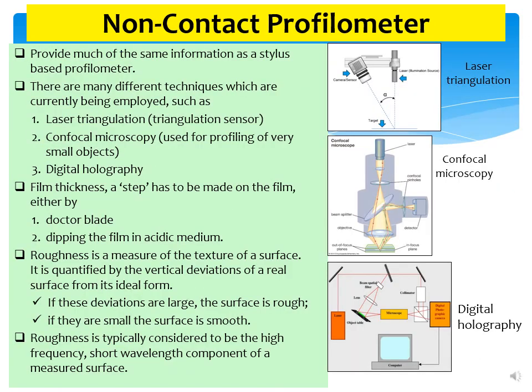In non-contact profilometry, an optical profilometer is a non-contact method for providing much of the same information as a stylus-based profilometer. There are many different techniques currently being employed, such as laser triangulation, triangulation sensor, confocal microscopy, used for profiling of very small objects, and digital holography.